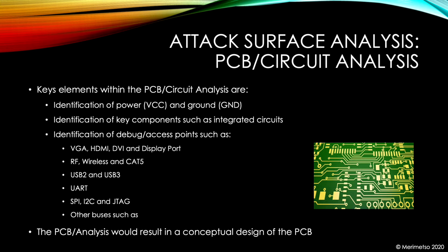The key part of identifying integrated circuits is that those integrated circuits will have pins that are communicating to the outside world. And if we can download the data sheets for those integrated circuits, we can identify the pins. And when we identify the pins, we can start attacking the integrated circuits to see what it can do.